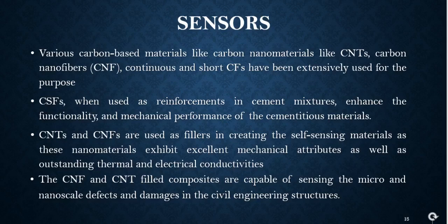ESF, which is used as reinforcement in cement mixture, has been shown to improve the functionality and the mechanical performance of cementitious materials. Carbon nanotubes and carbon nanofibers are increasingly used as fillers, and these create self-sensing materials, which have been shown to exhibit excellent mechanical, thermal and electrical properties. Carbon nanofiber and carbon nanotube filled composites are able to sense micro as well as nanoscale defects and damages in civil engineering structures. So, these are highly efficient.